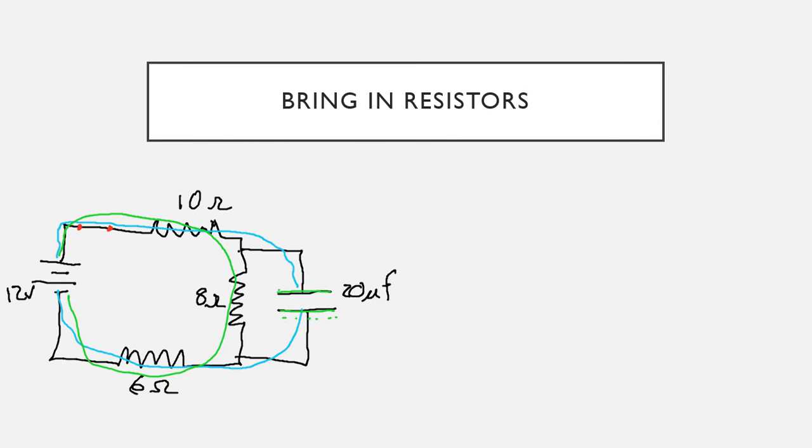So what we would see is initially more charges going this way, and then we'd see more charges shifting and more going through here. Now, once this capacitor is fully charged, well, that means no more electrons, and there won't be a side of positive charge either, right? So once this capacitor is fully charged, this path is done, right? So I'm not saying the capacitor is not there. I'm saying there will be no charges going through that. So then now all we'll have is a path through just the resistors.